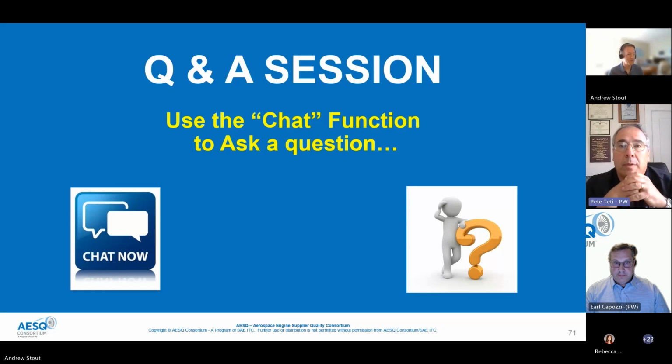Well, throw a quick one out there. CP will give you some idea of what's going on capability wise, but we don't like calculating CP or PP when the process is not stable, because by definition, it's not stable. Then there's assignable causes, and we want to eliminate the assignable causes. We want to understand what's driving the lack of stability.